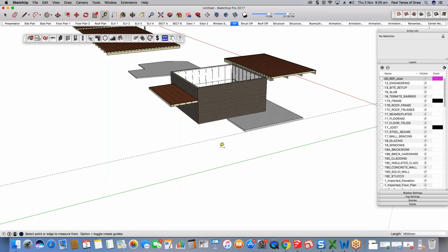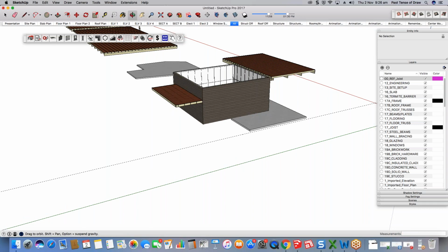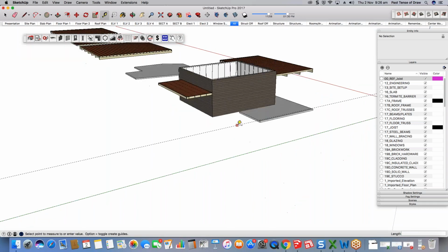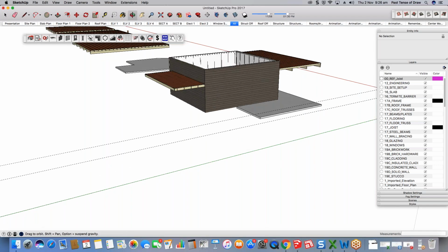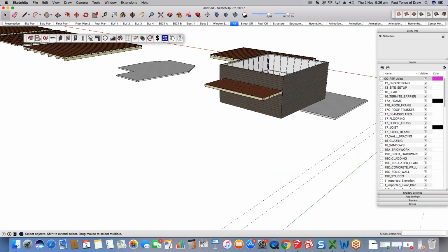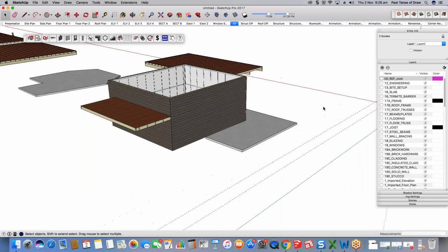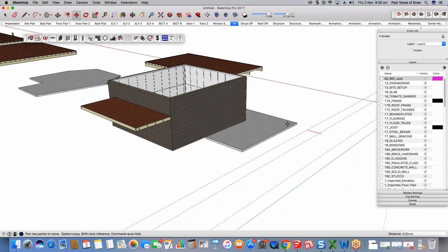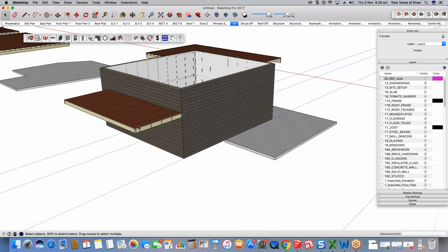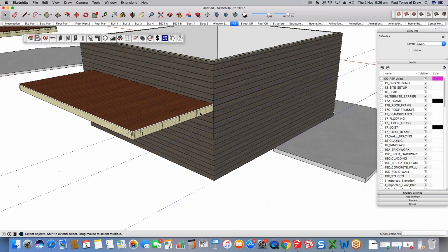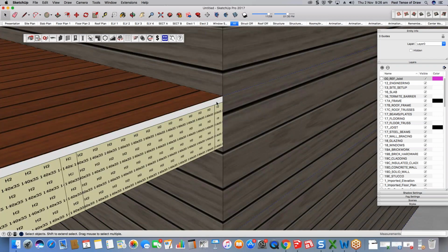Again, I can even reference the level in which I placed it. I can then reference the line itself, and I can really mass out the different things that I might need. So I might need another thing, say, that distance below it. That means I can now reference that. Now, all of these grids I've drawn out to the side, but these are movable too. So you can move them across, put them in, and assign them next to your actual model or project. They are on the grid layer.